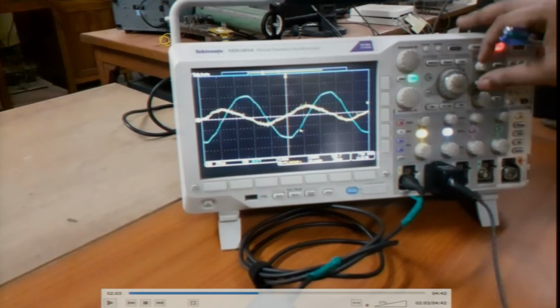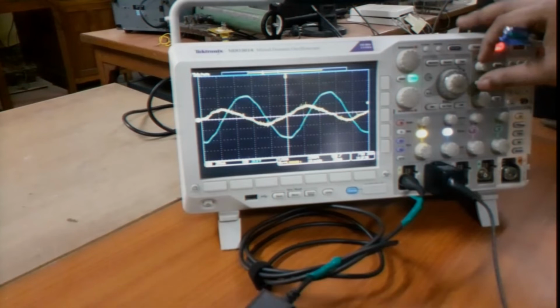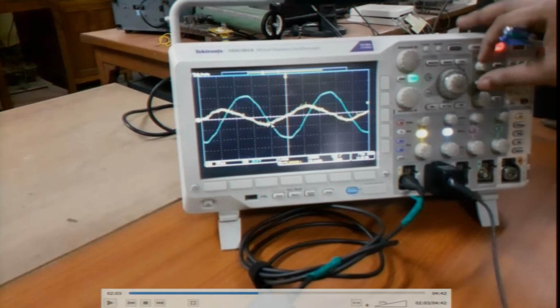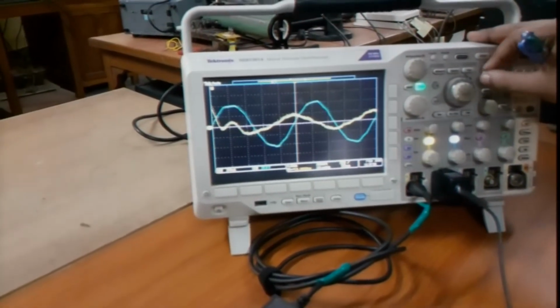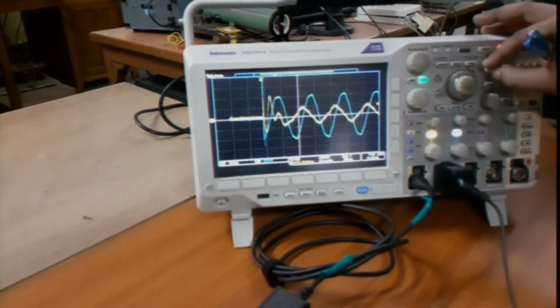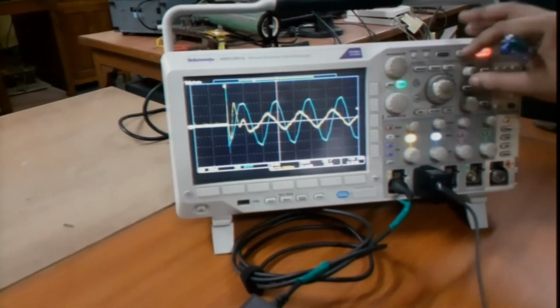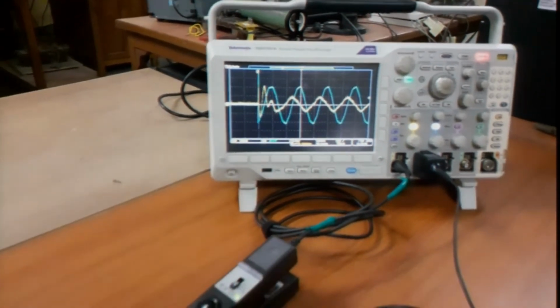The voltage which you are applying here is not a good sine wave, and what we get as a result in the sinusoidal steady state is not a very neat sine wave. It has got some harmonic components. So, although it is periodic, it does seem to contain harmonic components, and that is most likely due to the fact that this voltage also contains harmonics. So, you get a sinusoidal steady state response to a voltage which has not only one frequency component, but several.